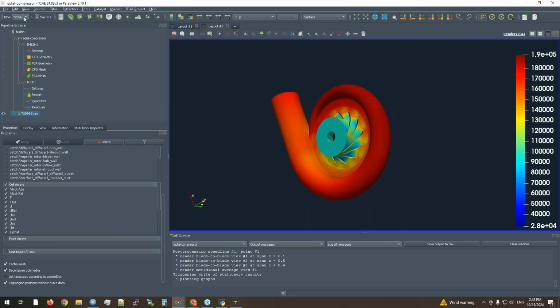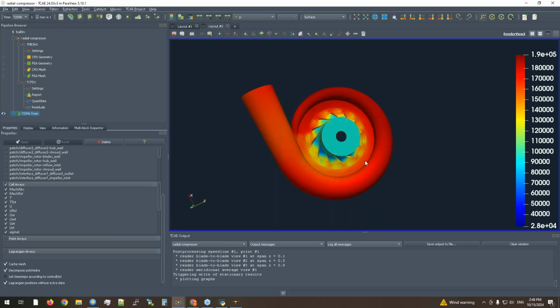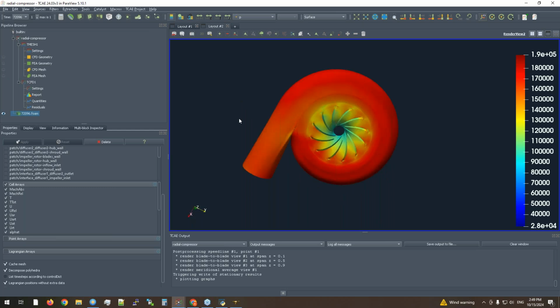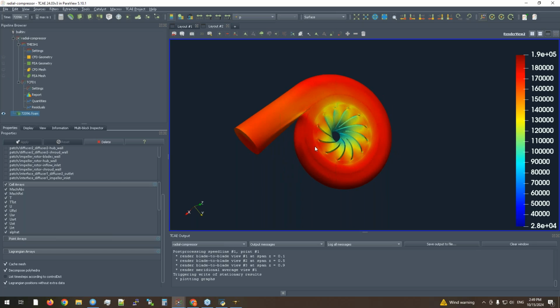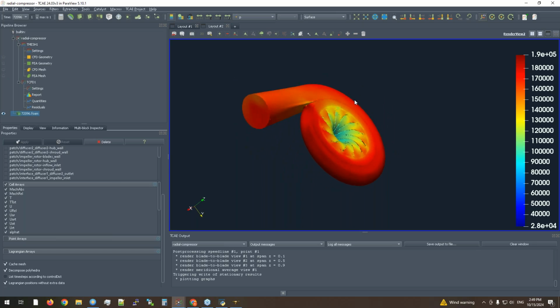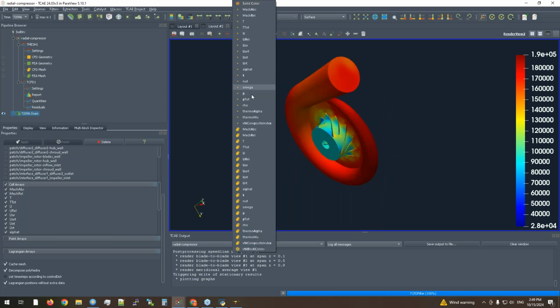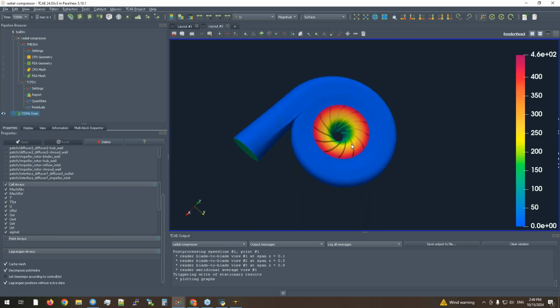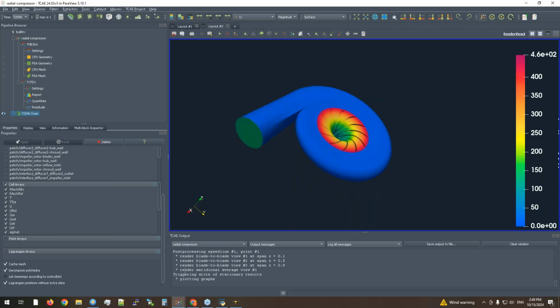Basically you have the time steps evaluated for the speed line, and the results for the current iteration which is running. So you can check visually if your simulation is running well and if all the quantities are converging. This can be visualized anytime during the simulation.